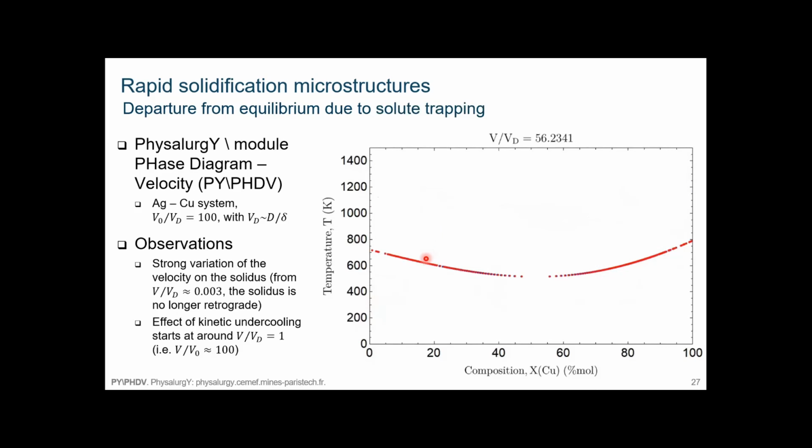So my message here is that we need to extend this methodology for multi-component alloys in order to be able to have a solute trapping effect on the growth kinetics and to have correct growth kinetics for this microstructure. So it's not just about computing colors with grain structures, right? We need to have good kinetics, and this is not done. This is, I believe, one of the challenges: to do that for multi-component alloys coupled with CALPHAD databases.